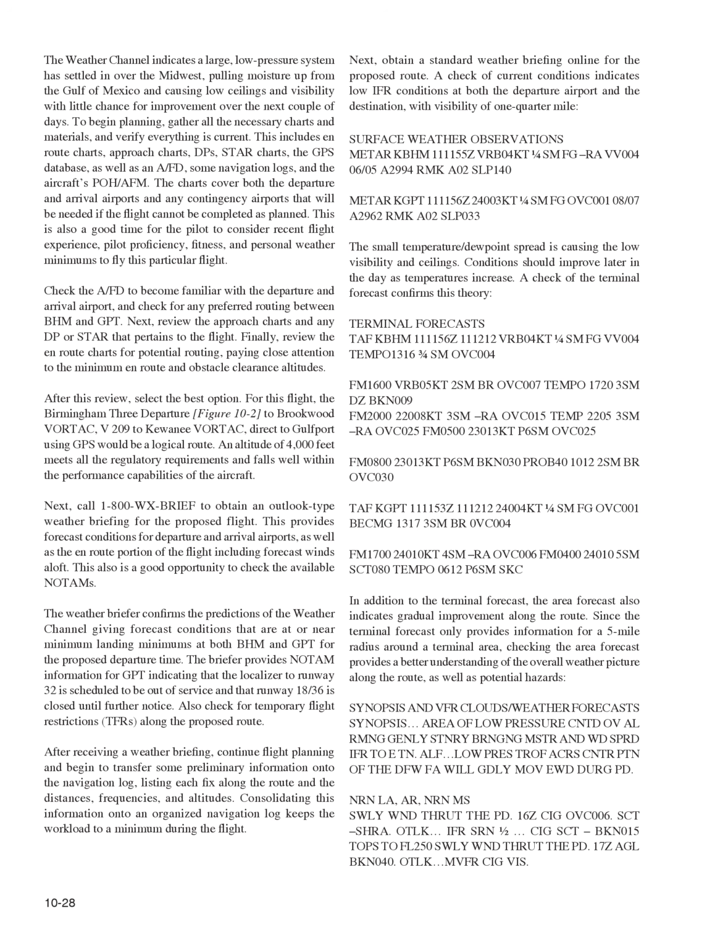For this flight, the Birmingham 3 departure, Figure 10-2, to Brookwood VORTAC, V209 to Kewanee VORTAC, direct to Gulfport using GPS would be a logical route. An altitude of 4,000 feet meets all the regulatory requirements and falls well within the performance capabilities of the aircraft.